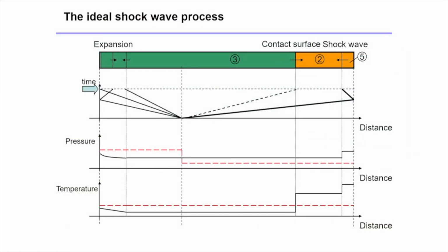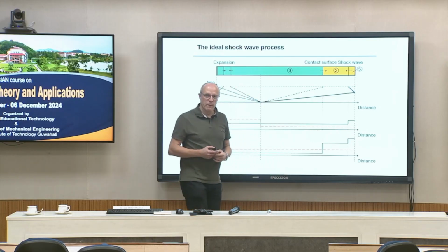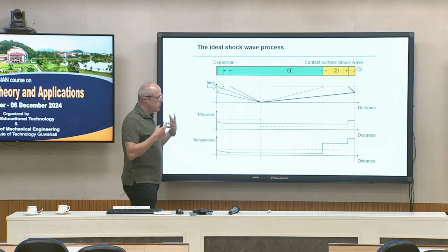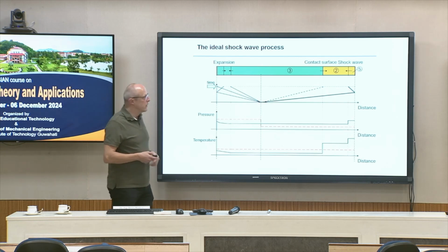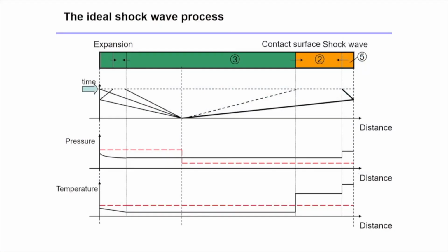So we have a further increase of pressure in a specific region, leading to a further increase of temperature. And this is what we are interested in normally, and this is the so-called section 5. As I've said, this is what you normally find in literature, the ratio T5 over T1.